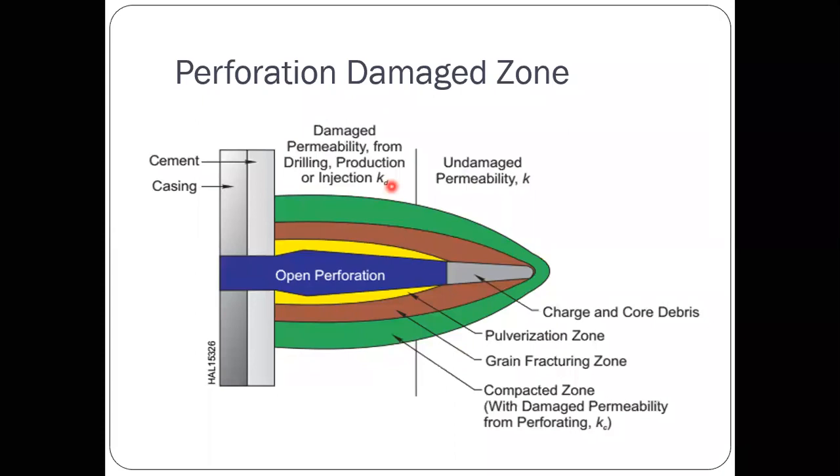And you also know that the effectiveness of the communication path through the cement and casing is very critical to the completion and the well performance. Whatever the path that we are developing, it will remain intact throughout the life of the well. And these perforations should increase the productivity in many ways.